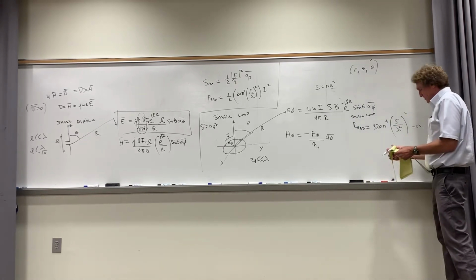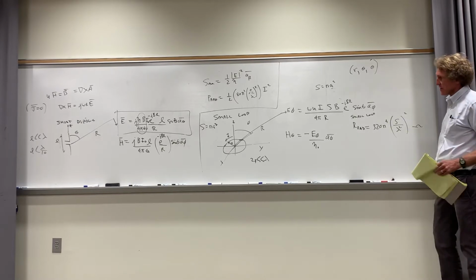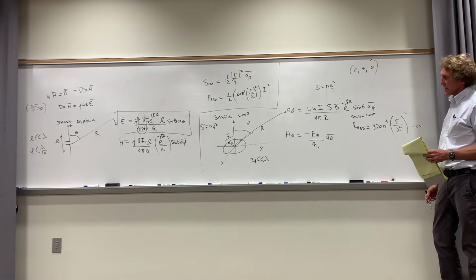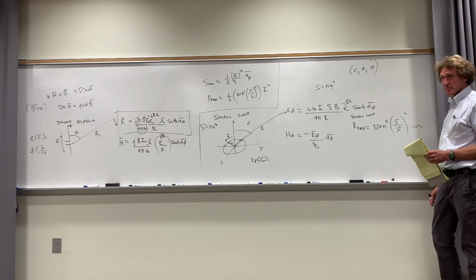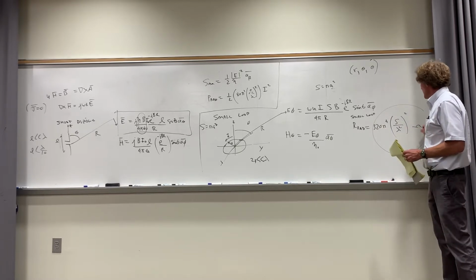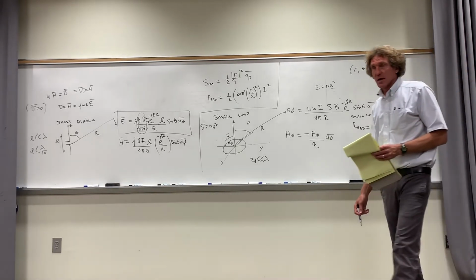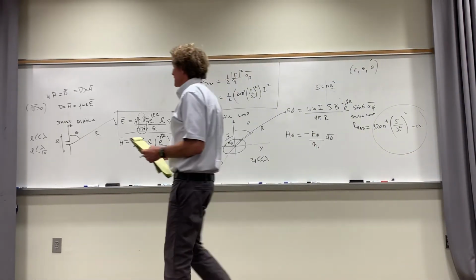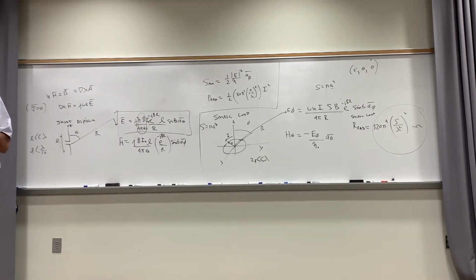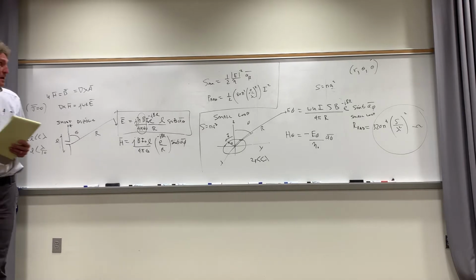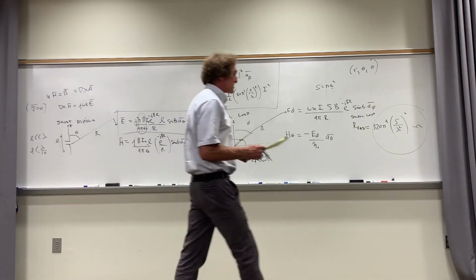Now, you'll see that in his book, but remember, S is the surface area. It's really the area contained within that loop, the loop's circumference. Do y'all see this, class? Somebody should ask me, do I need to remember this equation? Answer is no. By the time you get done with every possible antenna configuration, you'd have a lot of equations, and just memorization of it's no good. You have to know how they actually kind of behave. Are you with me? All right, but that's the radiation resistance.